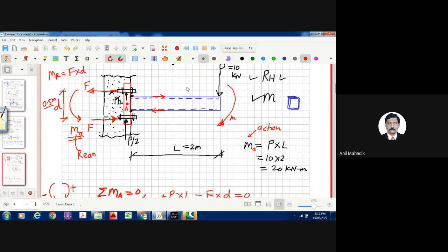That means these two bolts are taking the vertical reaction, they can take the horizontal reaction, and they can take this moment also. I hope you got this. And this is the fixed support, practically speaking. समझ में आया support? Yes, sir. So this is the fixed support because three reactions are possible.